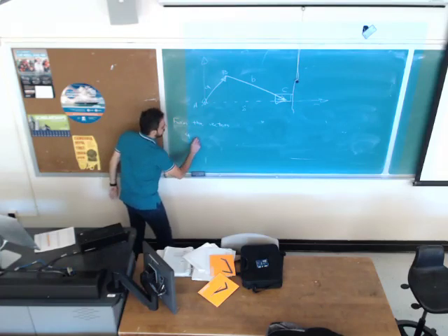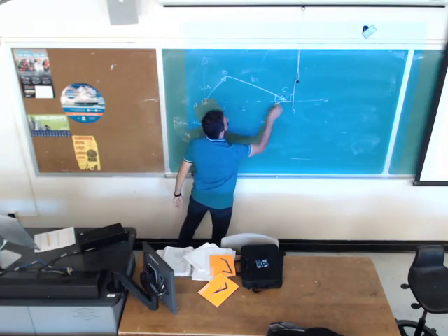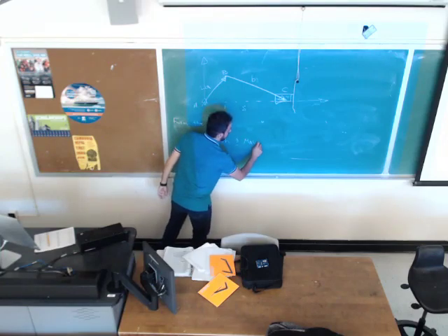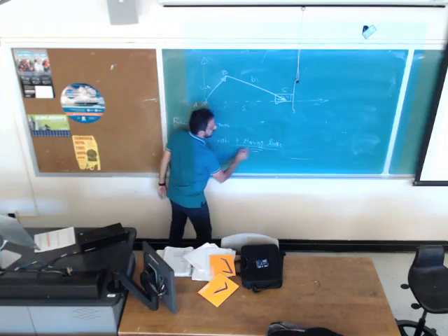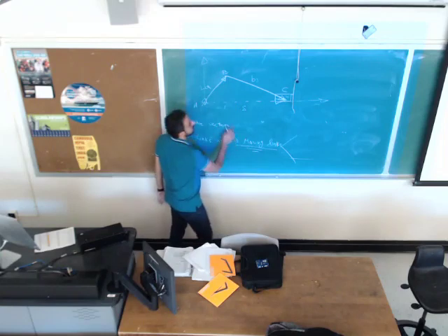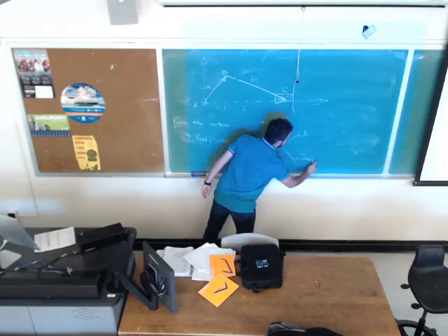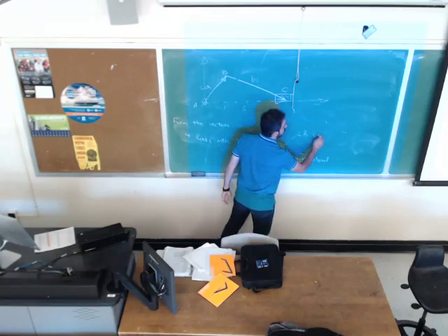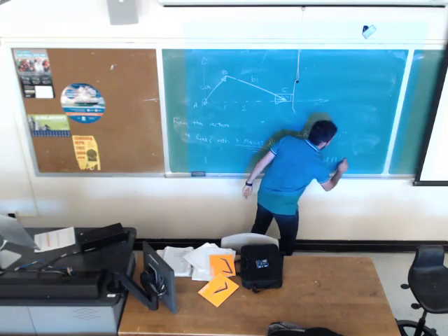So we have 4 links: 1 ground, link 2, link 3, slider number 4, with 3 moving links. So I'm expecting 3 variables. Out of 3, 2 have rotational and 1 has translational motion. So 2 rotational means I'm looking for 2 angles, theta, and 1 distance as a variable.